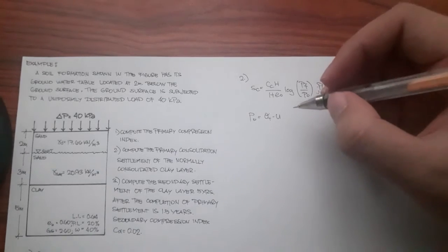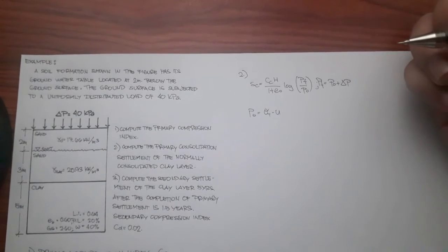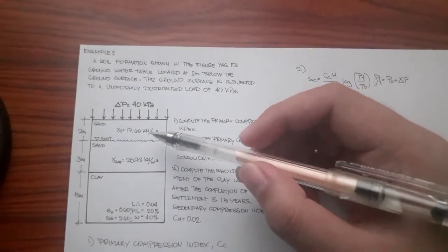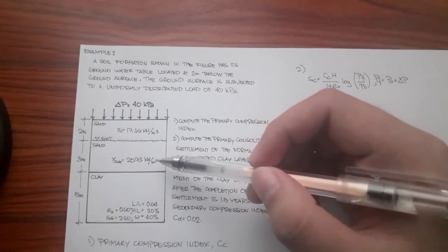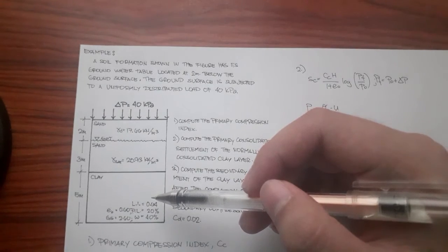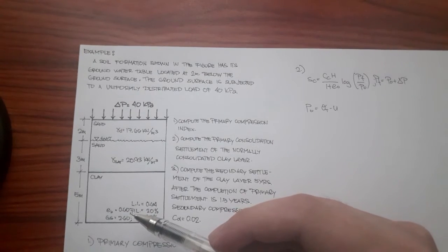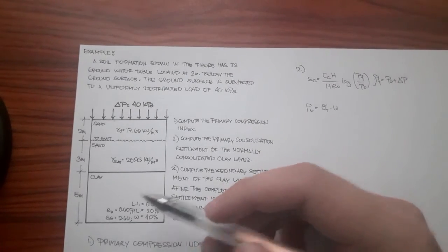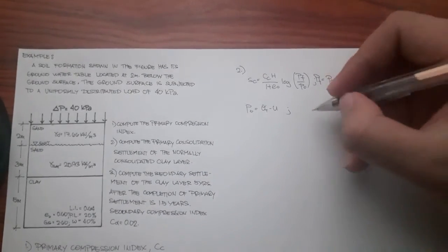And since in finding the value for our effective stress, we need to gather the values for our unit weight per layer. Here in the illustration, gamma dry is already given in sand, and the gamma saturated for our sand is also given. However, the saturated unit weight in our clay is not given. However, we are given the specific gravity of 2.60 and the void ratio of 0.60, which are components in finding the gamma saturated in our clay. So, we need to find first the value for our gamma sat.